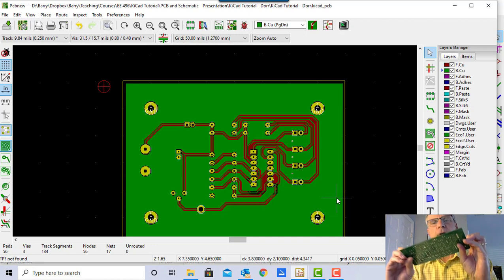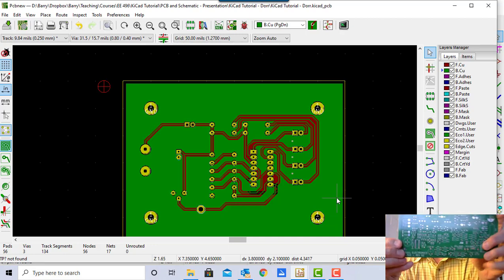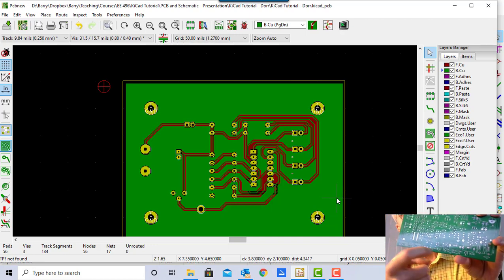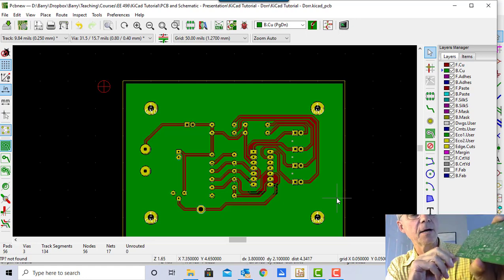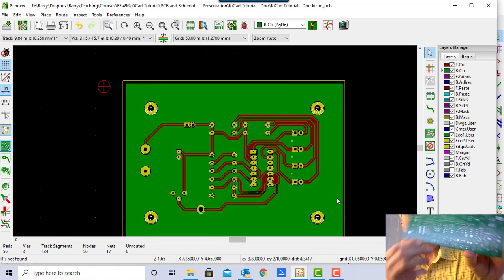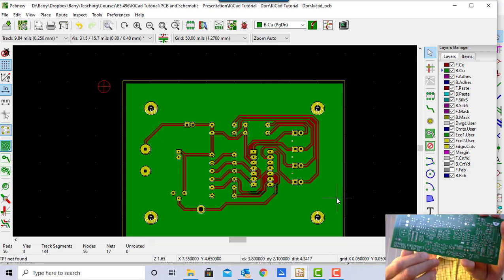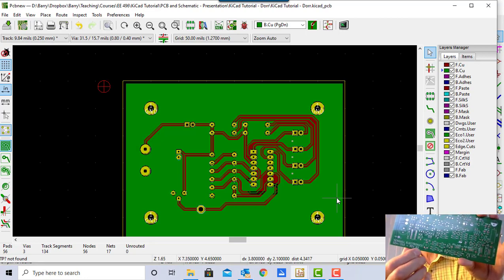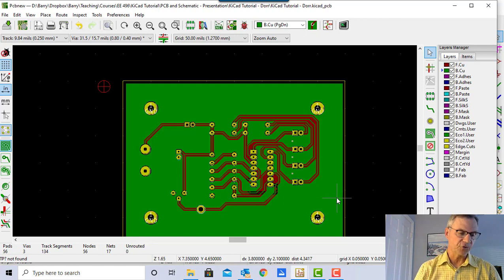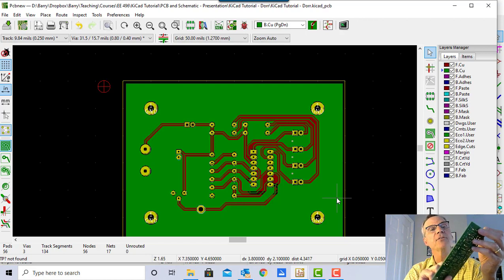If you look at this board, you probably can't see it, but you can see maybe my Siegel Electronics SEA 310 revision Q2, and it's written in white. And that white writing is what we call the silkscreen. That's kind of the traditional name for it, and we still use that name. So the silkscreen is white lettering on the board that helps you assemble the board and debug it.